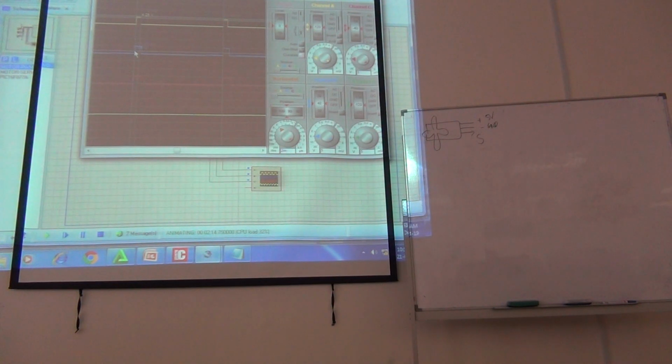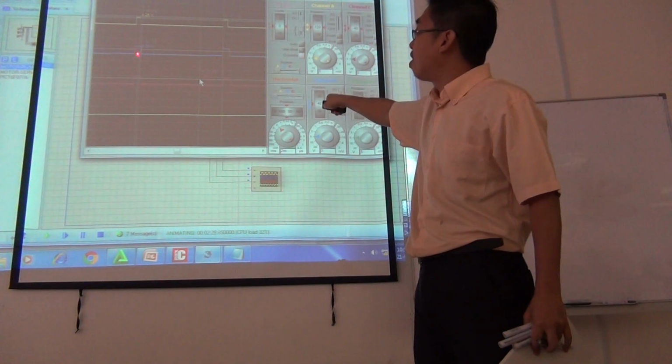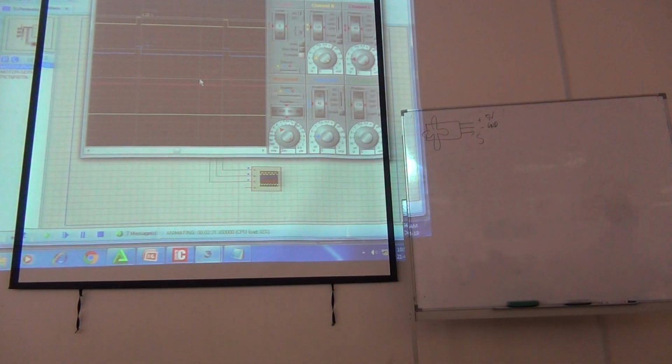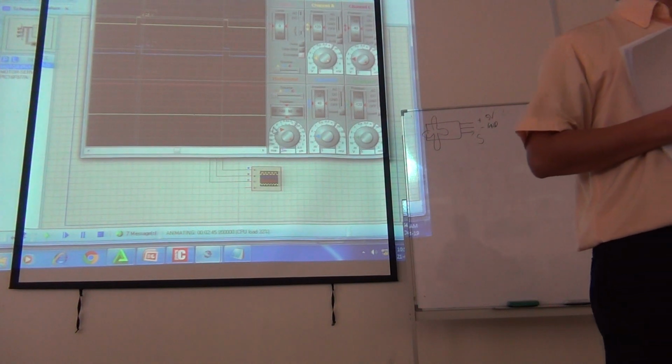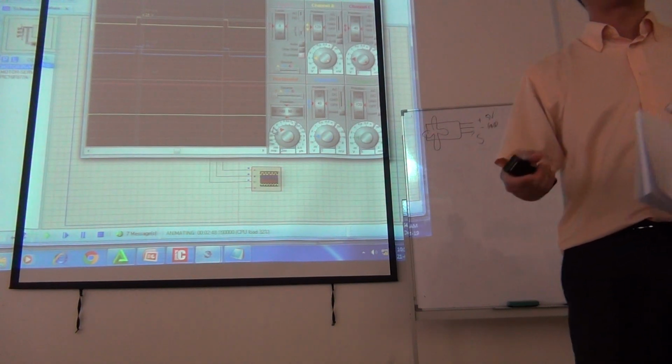Right, let's look at the other PWM. This one is at 0. This one is at 1. Around 1.4, 1.5, something like that. My cursor is not really good. One is around 1.4, and this one should be around 1.7 if I remember. 1.9, sorry. 1.8. Okay, this is how you generate the PWM accordingly. But we are going to learn Timer 1. I give you the code first, you run it first, look at the result first.